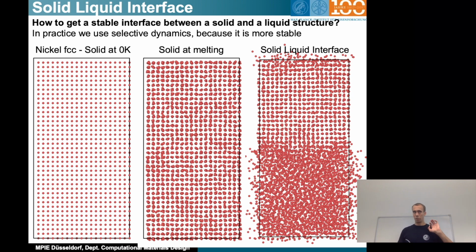What we do is we start with the solid sample, we heat it close to the melting temperature, but it's not yet molten. We then freeze half of the sample and continue heating the other half. Right? A feature like selective dynamics is currently commonly implemented in all modern codes, but it's something that was not so commonly used previously in multi-point calculations, or what we didn't see before.